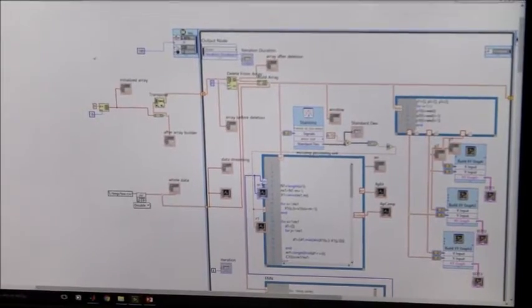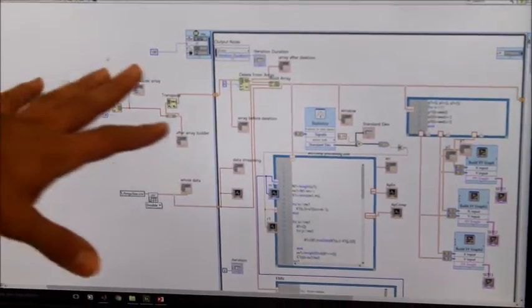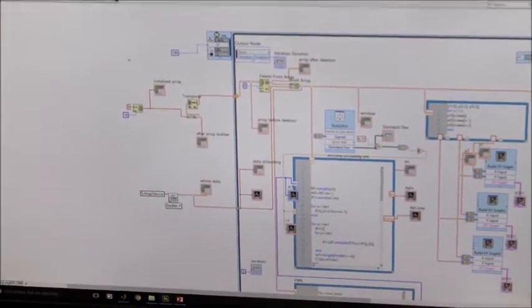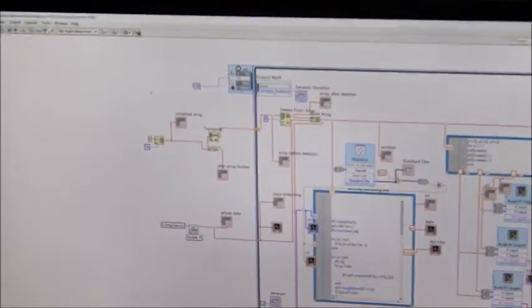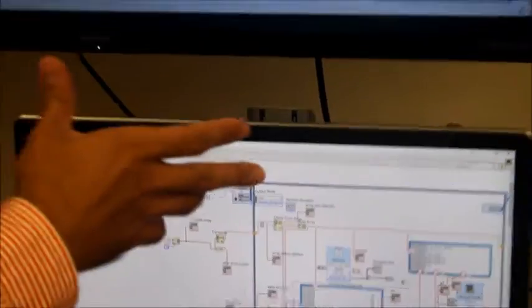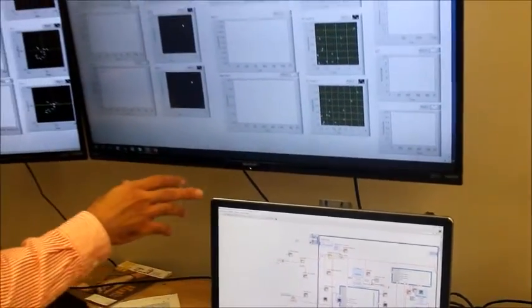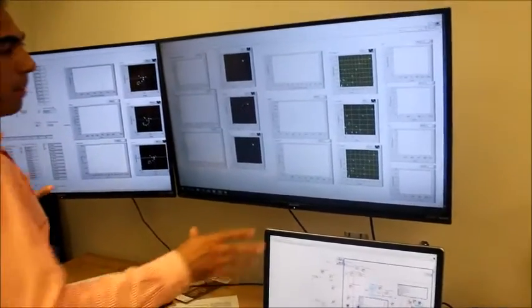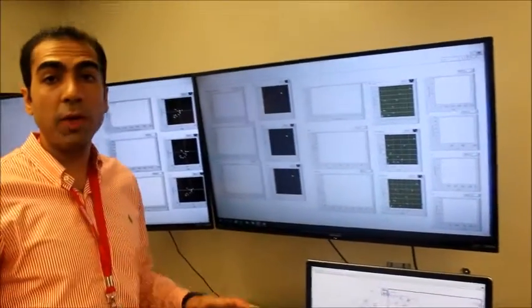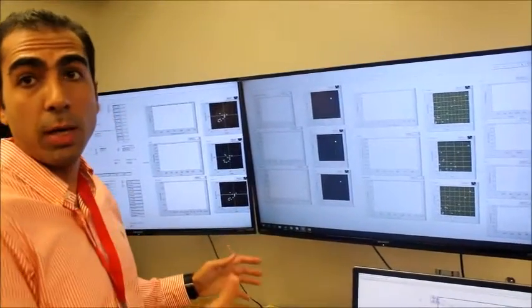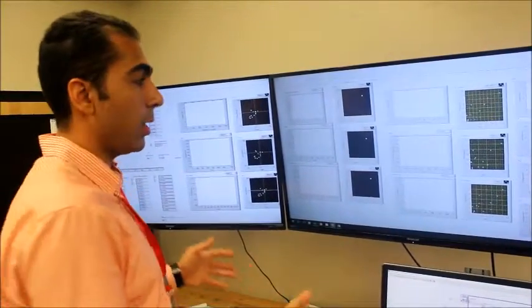Intentionally, I have increased the step time here from 2 milliseconds to 100 milliseconds in order to make the visualization better. The reason why I increased the step time intentionally is that I want to make the simulation slower, because if I choose 2 milliseconds here, all the simulations will run in real time, which is 2 milliseconds, and it's really fast.